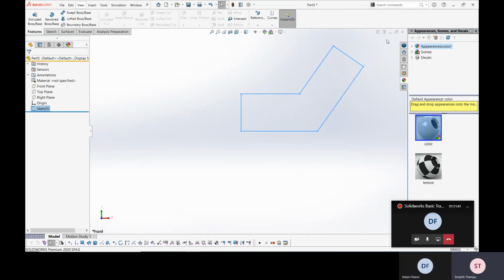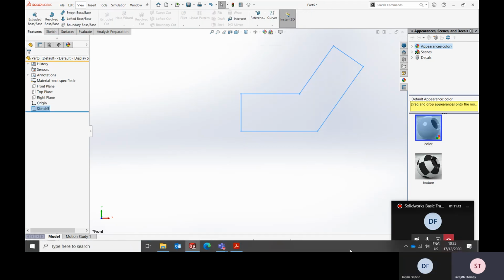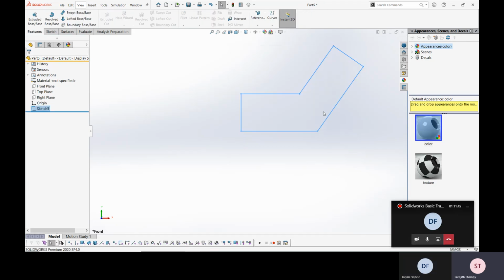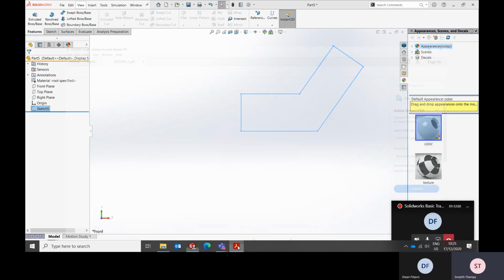So those are the different stages of a sketch. When you are having an error, like an over-defined or under-defined sketch, or an opening in a sketch, for all these things we have the Sketch Xpert and sketch checking options in SolidWorks that can help you in resolving the issues, which we will be learning in the coming modules. So let's continue.